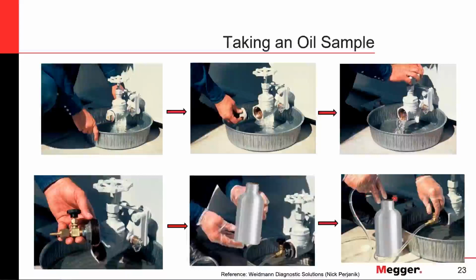I will also say the flow of oil should be gentle and constant from when you start those initial flushings of the container until you finish the last filling of your last container, in case you're filling several containers. Again, the flow should be gentle and constant. By that I mean you should not interrupt the flow of oil between the flushes or between different containers.